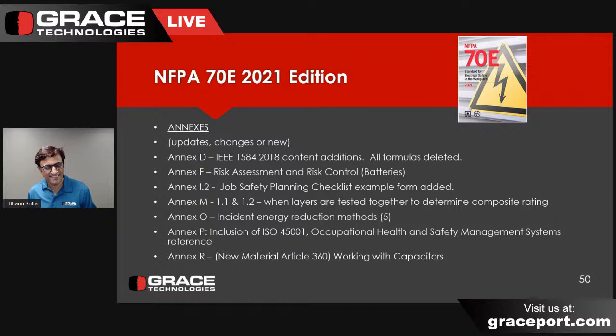Most of what industry's done is gone with a single layer, coverall, a shirt or pant, and then you go right to an arc flash suit, which again was emphasized with the addition of Table 130.5(G), right? So basically, total system arc rating should be managed by you if you just buy everyday wear and an arc flash suit. And an arc flash suit is a tested multi-layer system, either the bib overalls, the jacket, and the hood by the manufacturer of those arc flash suits, all right? And then ISO